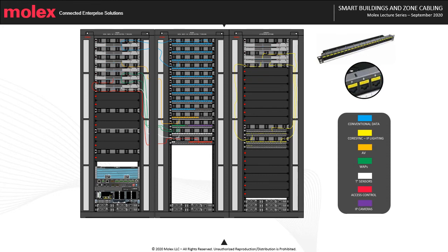In conclusion, for our conventional cabling system design, we will need 3 racks. We will install 8,712 meters of cable, that is 28,577 feet, and we will need approximately 10.4 days of work for 2 engineers on site with 7 hours of work per day.